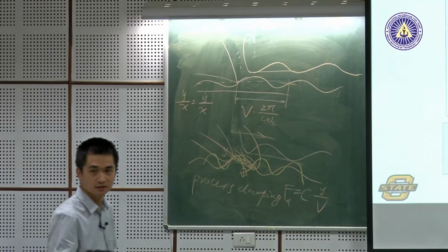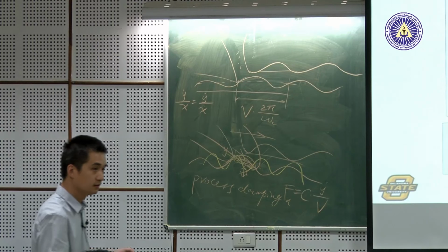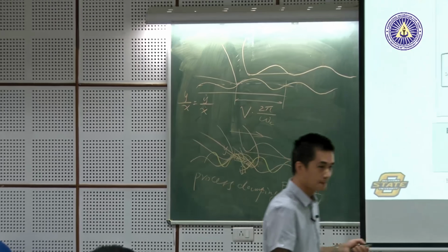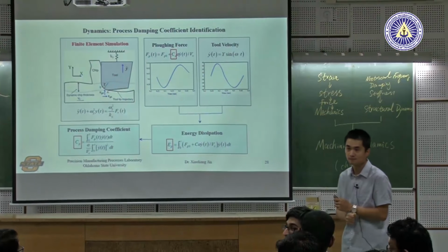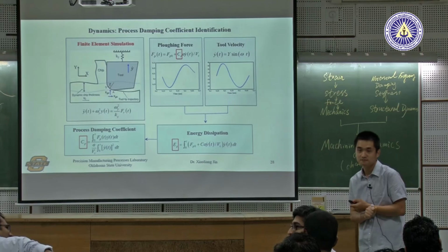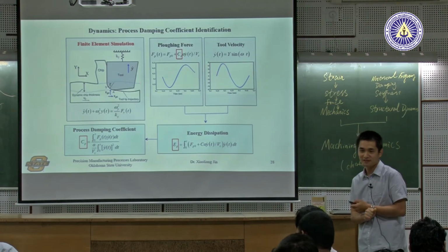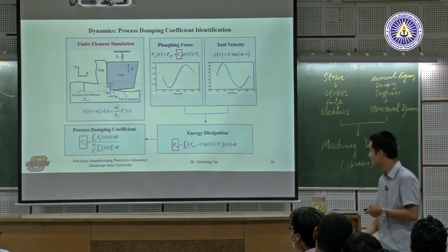Which means a larger critical depth of cut from the chatter point of view. And there's a lesson in this for our cutting tool makers also. A smaller clearance angle might be better for stability, because when you have contact, it lets the tool wear out. The thing is that if you have a 30 degree flank, it makes the tool tip chip, right? So there's always a balance.